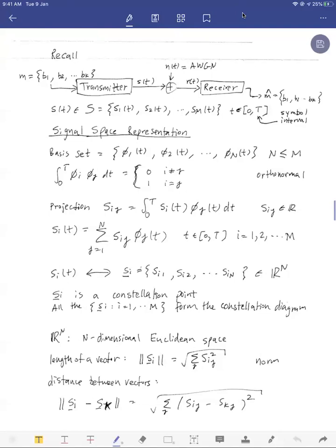we have a set of bits here. So M is my input message, and it's going to come from a set. So it can be one of any. So I wrote B. Maybe it's fair to call it symbols, right? It could be bits as well, or pairs of bits. So we have in this instance K symbols that we want to transmit, and what the transmitter does, right here I'm modeling just the digital modulation part of it. The transmitter is going to map the information I want to send, the bit or the bit sequences, to a transmit waveform, right? S of t.